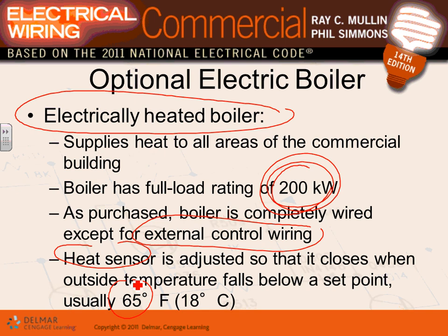When it's 65, guys, it starts the boiler. Now the boiler is up and running. Doesn't mean it's heating. It's just up and running. It has enough juice in it to heat if needed. Any comments, guys, about this external sensor that interfaces with that boiler?